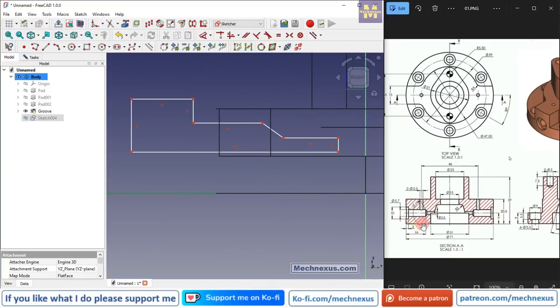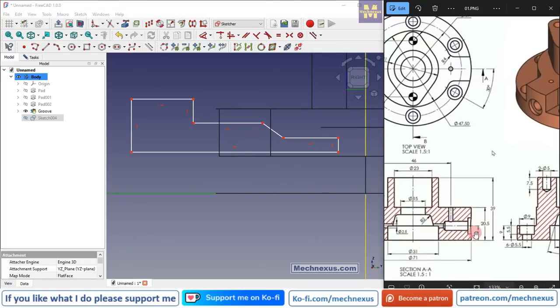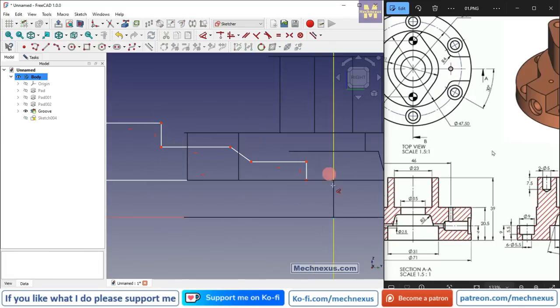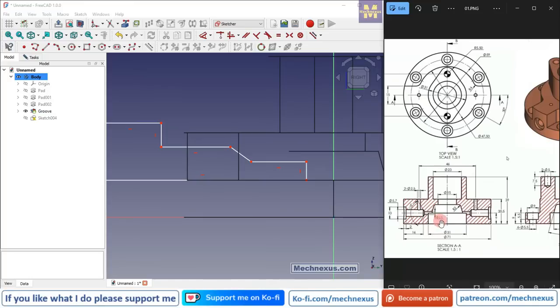So from this bottom edge to axis is of 9 mm. If you zoom it, we can see here it is 9 mm. So this is our bottom edge. Select a dimension from this to this. We'll provide 9 mm, and now zoom out, and here is a diameter of 2.5.